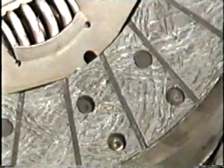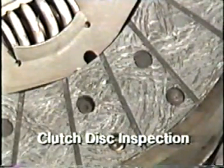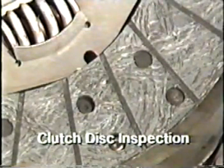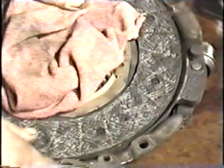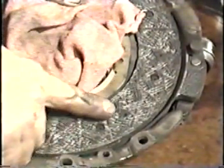Now let's check the clutch disc wear. To check clutch disc wear, you need to inspect the wear lines built into the disc. They fan out from the center and can show wear across the disc's entire surface or indicate wear patterns where the disc is wearing selectively on one side, possibly indicating a housing alignment problem. These wear lines indicate the disc was badly worn.